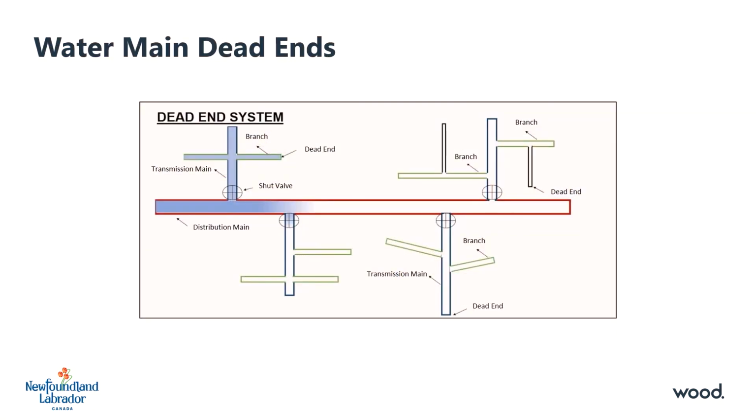Water distribution systems in many Newfoundland and Labrador communities are treed or branch type configuration. These systems contain long linear sections of water main that leads to a dead end or multiple dead ends. In order for the chlorine residual to reach all points in the water distribution system, there must be enough flow throughout the system to move the chlorine from where it is injected at the chlorination building to the end of the distribution line. Residents and businesses using water is normally how water flow is created throughout the distribution system.